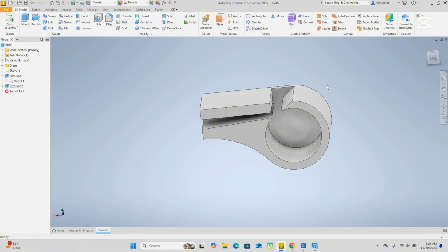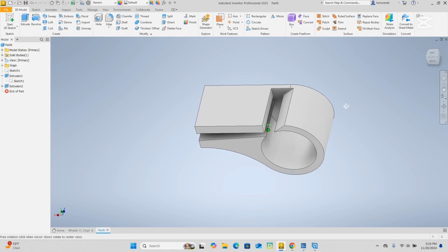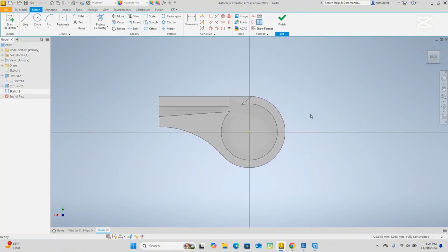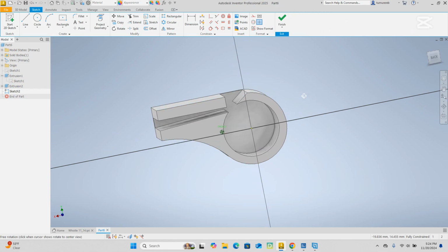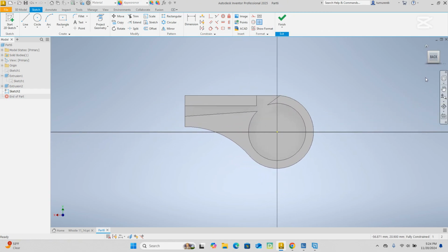All right. Now, what else can we do? To do this side, this side looks like this. This is exactly what we need to do. Now, do we have to start a 2D sketch, draw a circle, draw lines like we did before? Or we can be smart about it. We can be more efficient. Take the advantage of what? Project geometry.